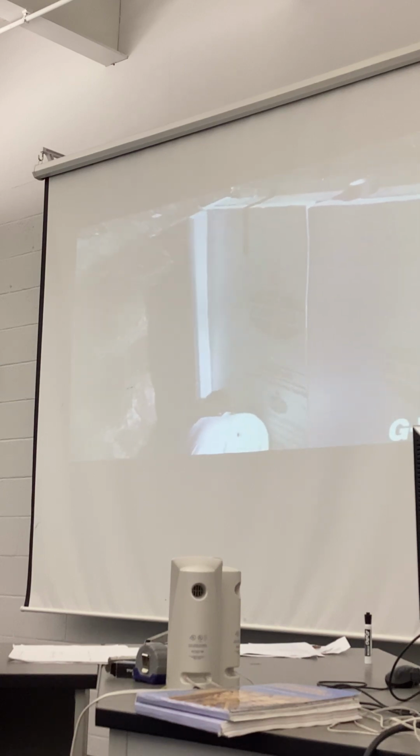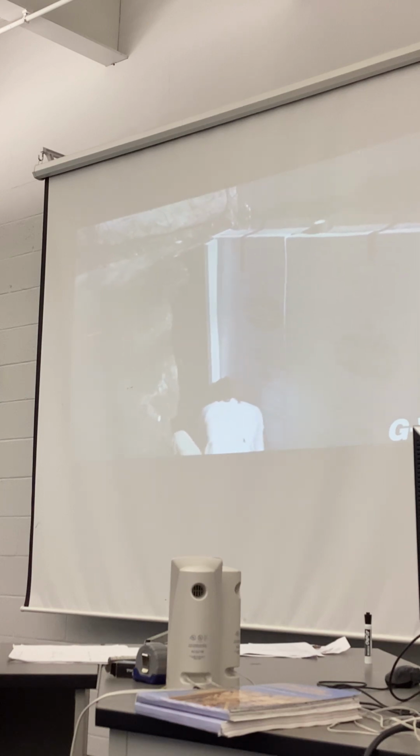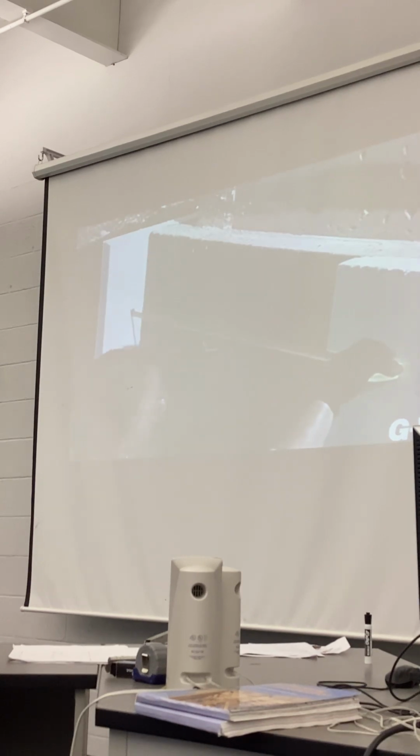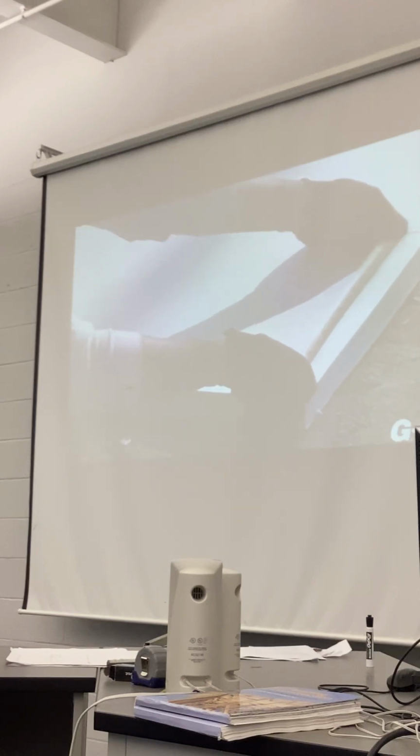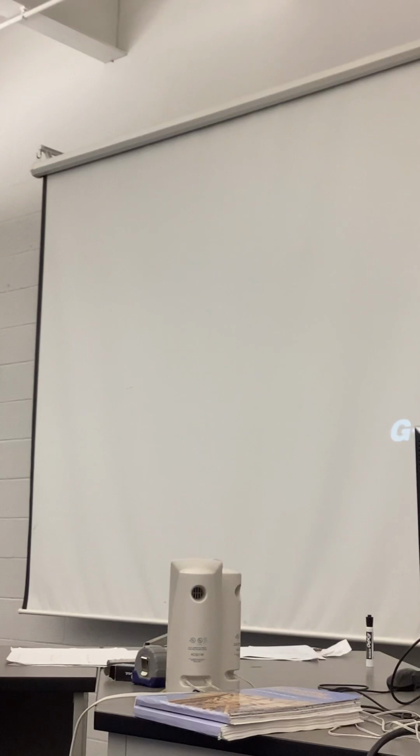A handsaw is often used to cut thick insulating board to size. The foam board is marked for the cut and then can be easily sawed to size with a handsaw as shown.